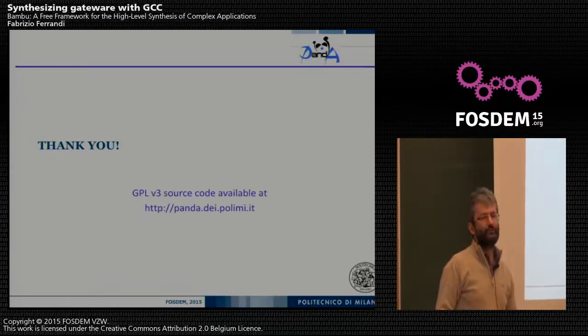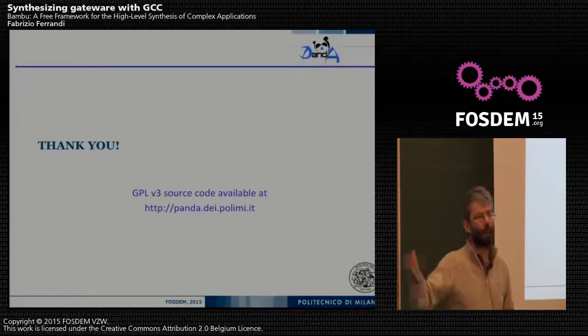So the idea is to reverse engineer the VHDL into C, and then have something that could be retargeted to any kind of hardware and so on. It's a matter of designer fantasy. I did such things, for example, for floating point cores.